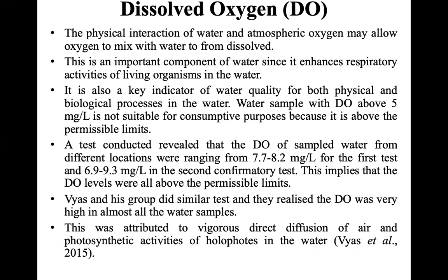In other jurisdictions too, some water, especially water that is used for other purposes, should not have low dissolved oxygen. And so as a water quality indicator, it must be determined. Now, if you have a stream and you realize that aquatic organisms are dying at regular intervals, then you, the investigator, must use your probe to measure the dissolved oxygen content to see whether it is high enough to support the aquatic life.